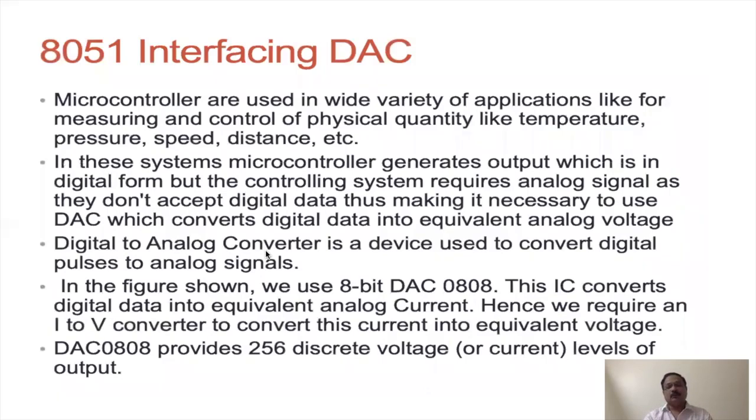Now ADC will be used at the input side of the microcontroller. However, once the microcontroller processes that input and gives the desired output, that is in the digital form, but to the external world, that should be converted again back into the analog form, and that work is done by the D2A converter.